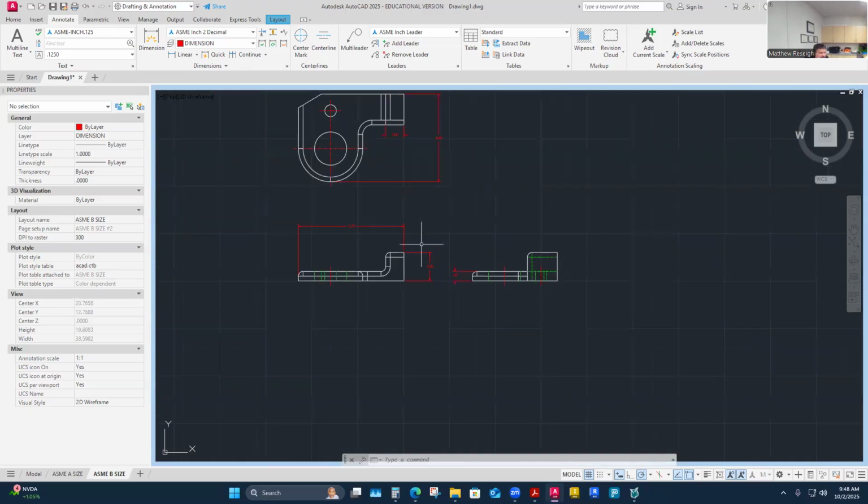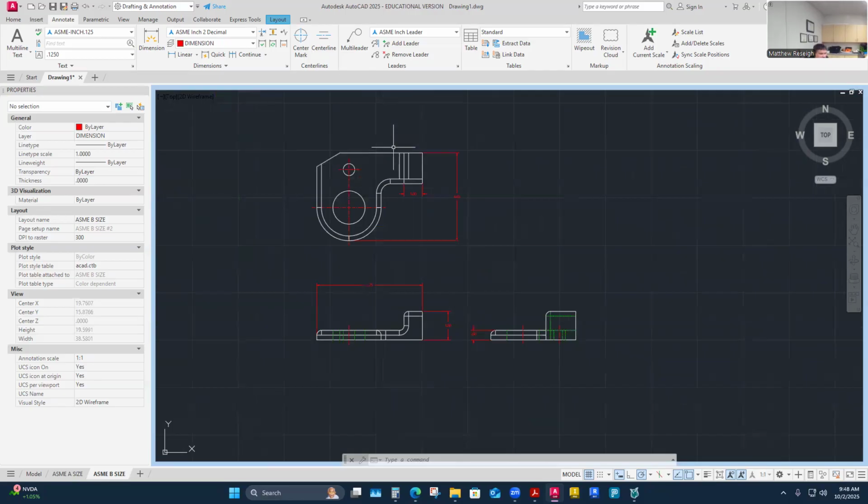Location gets a little bit vague on this, because I think I've locked in size, but what is the location of it? Well, a location might come from dimensioning it to some other feature on the part. I think I'm going to lock in a location for that, maybe when I start to lock in some of the other feature dimensions, and they may become kind of dual purpose.